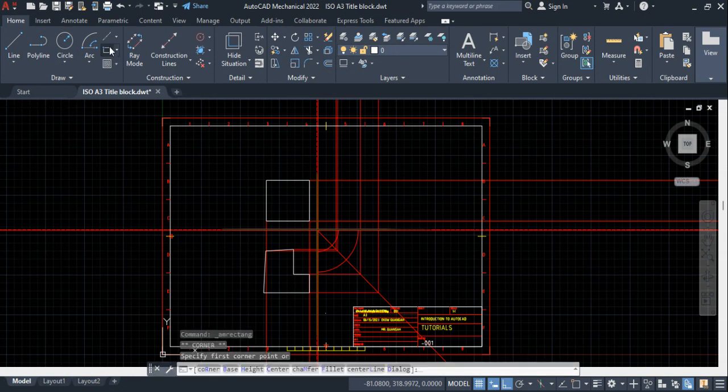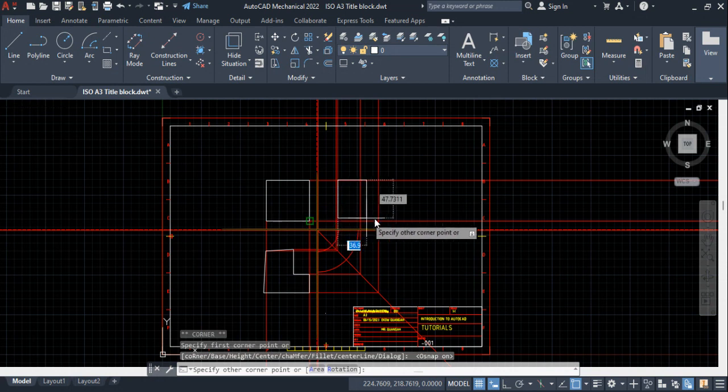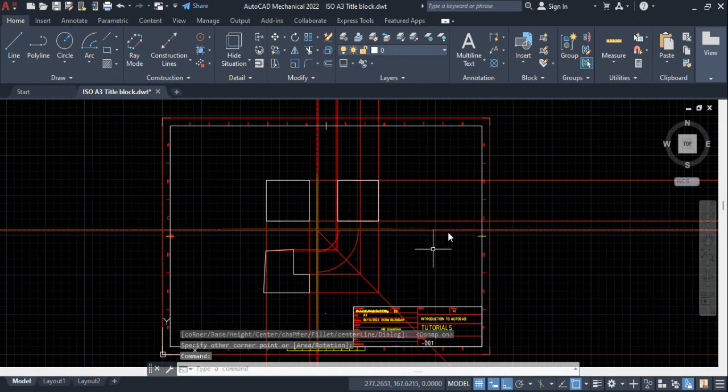Okay, so select maybe any of the rectangles or a polyline, depending on what you want to do. Let me try and select this. Then let me bring back my object snap because I need to get some snaps here so that I can get what I want. So with this help, you have drawn your side view with the help of construction lines.